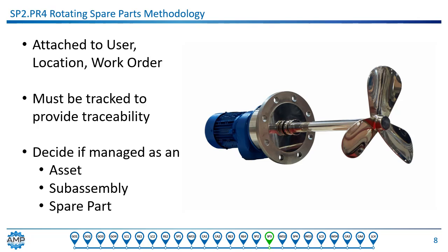Is it used in batch production? If so, the entire tank assembly might be disassembled, the various parts and subassemblies cleaned, then stored in various locations to later be assembled interchangeably with other parts to form a functional process mixing tank. In cases like this, identification is key because of equipment traceability requirements related to batch records. Each rotating spare part has a physical and virtual record, just like an asset.